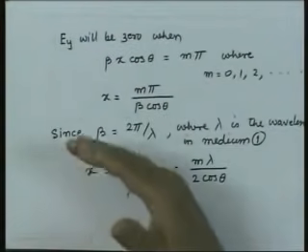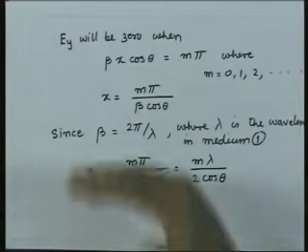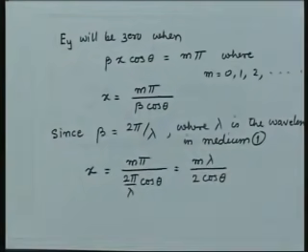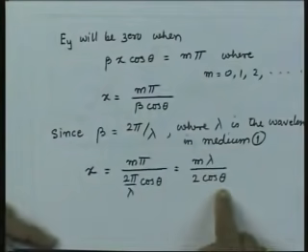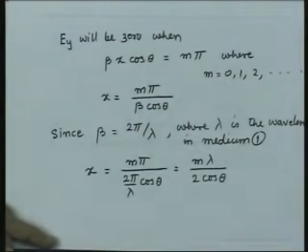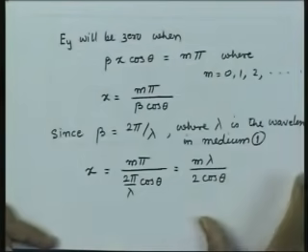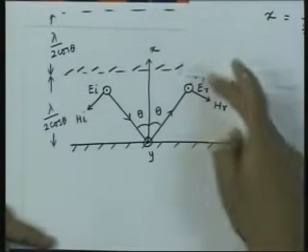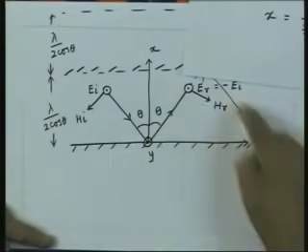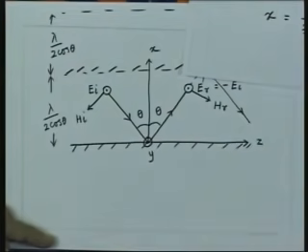If I invert this relation, say, well, the separation between the plates is given, and let us say that is equal to d. Then what are the angles at which, if the wave is launched, the propagation will be sustained? That means it will satisfy the boundary condition, and the wave will propagate by these multiple reflections around the boundary.